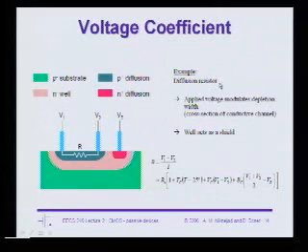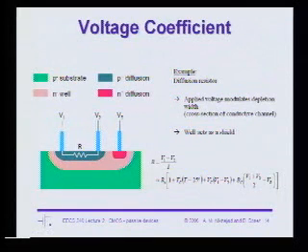So you can see that the resistance changes based on the difference in voltage and the average voltage, right? The average voltage would be this voltage plus this voltage divided by 2, assuming that the voltage variation here is linear, probably a pretty good assumption. And the difference voltage is really the fact that if you have a really high voltage over here and a really low voltage here, the depletion region widths will be different, so it's not a uniform thing. If you were to put roughly the same voltage across here and just apply a small differential voltage, you would still see a variation in resistance. This is captured by these two moments, the average moment and a difference moment.